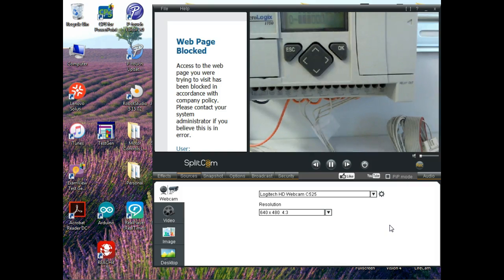So you got these people that come up through computers, then they have a language that they wouldn't have to learn ladder logic to do what? To program a PLC. And then you have a language called function block programming, which basically is where you use symbols to program, logic symbols like ands, ors, nands, nors, nots, and you program it with the symbols instead of the context. Those would be for people that come up through electronics and through digital and stuff like that and haven't had PLCs.